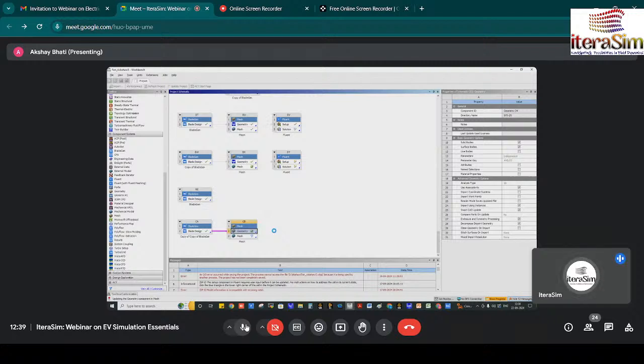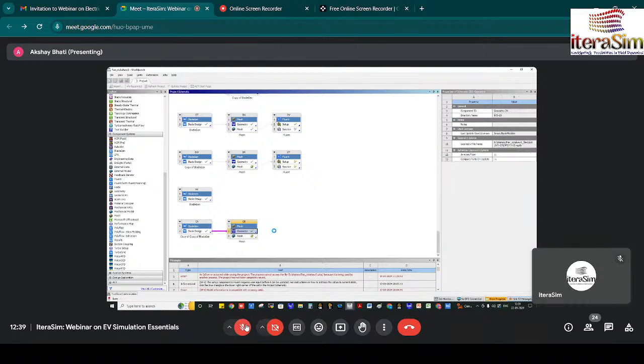So for eight blades you are taking, how many elements would there be if you are doing meshing? Actually, in turbomachinery we require some fine meshing. So if we go in Workbench meshing, it would be around 55 lakh elements, depending on the size of the fan.